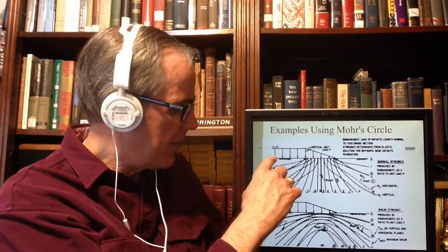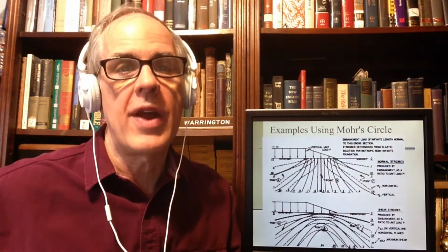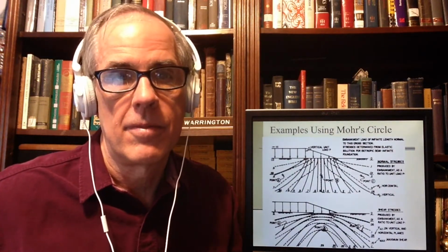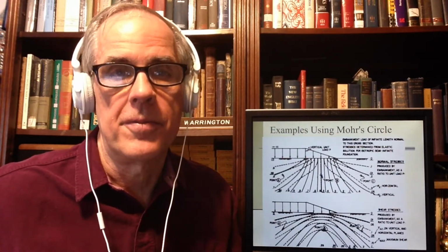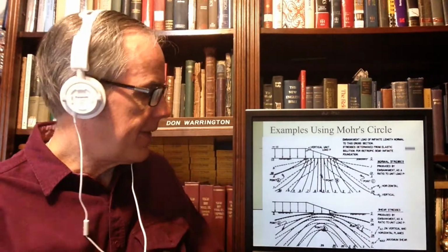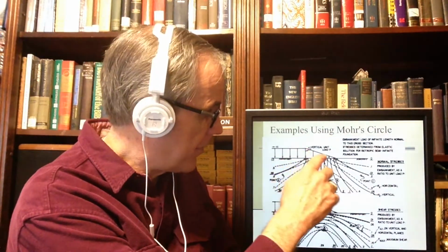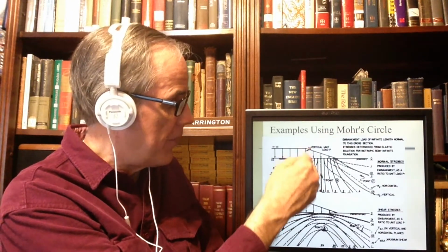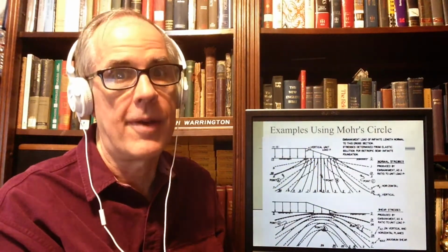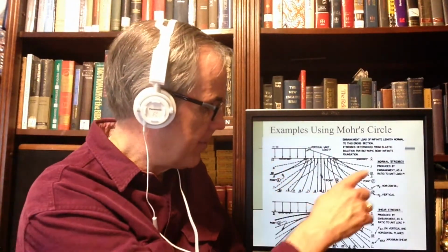The pressure that this surcharge exerts in this area on the ground is equal to the unit weight of the surcharge times its depth. And that's a surcharge load. Now, in this particular case, everything comes to an end, and then it slopes down. If it were cohesive enough, we could do a nice cut this way, and we're going to talk about that. But when it slopes down, the loading under it is complicated, as you see.